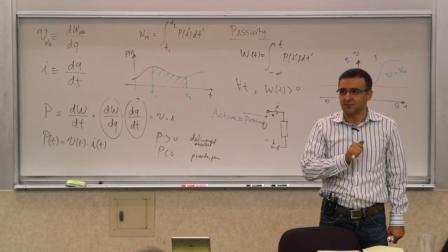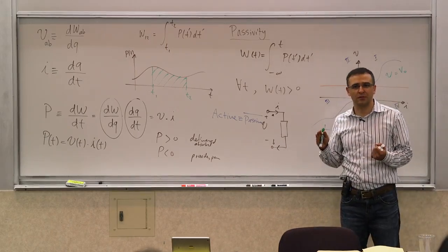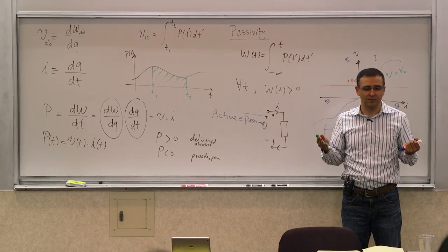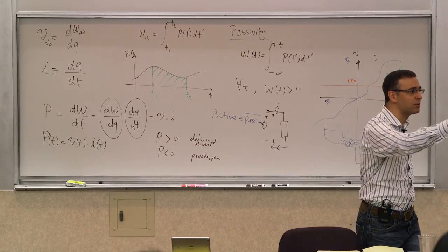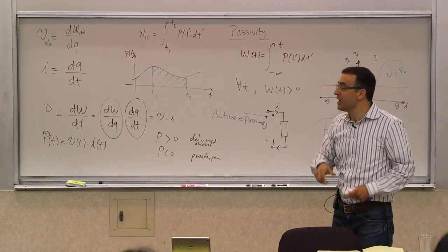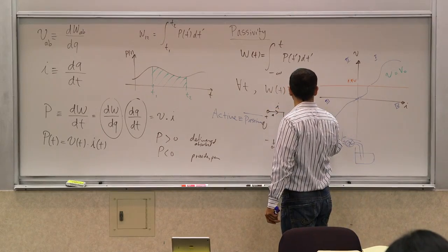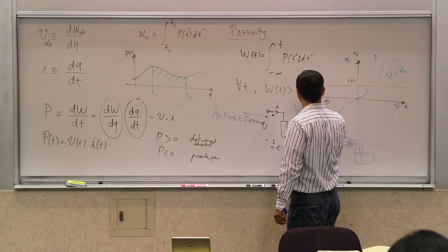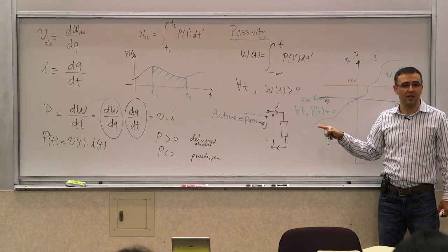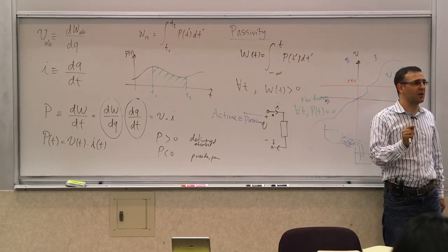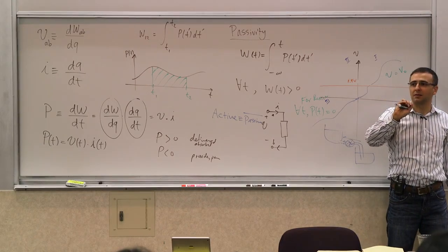But going back to the capacitors, right? So capacitors technically are what? So what conclusion do we arrive at? Passive or active? Passive, right? So they're passive. However, they're a special kind of passive. They are passive that at some point can provide energy to you. A resistor cannot. For a resistor, actually, not only this is true, but this is also true, right? Because of this IV characteristic. In a resistor, even the instantaneous power cannot be negative. There's not one instance where it can actually provide power.